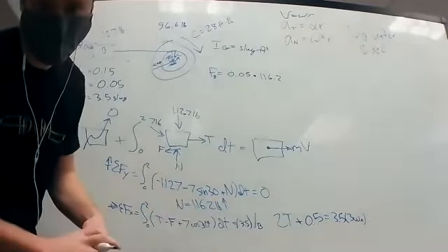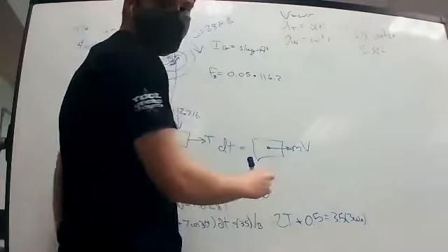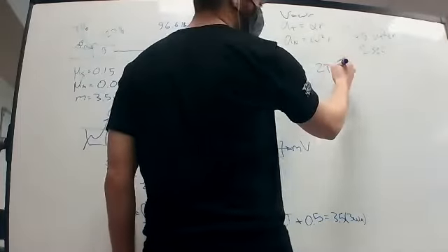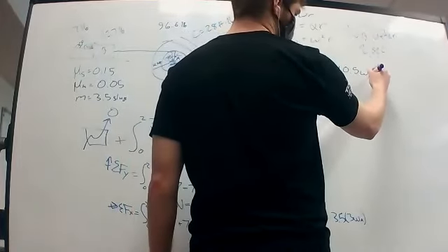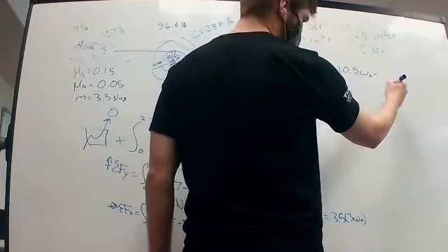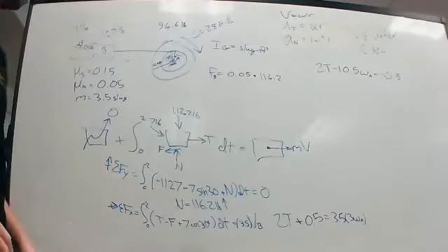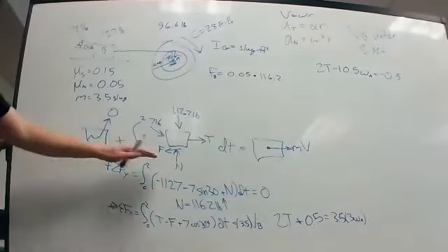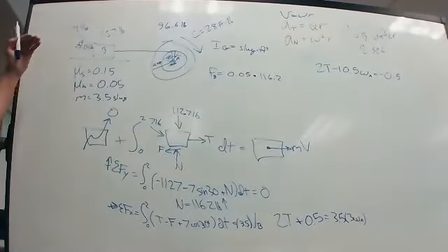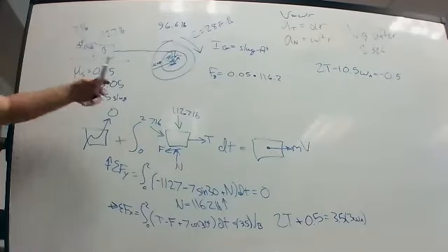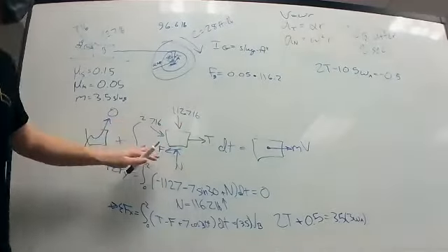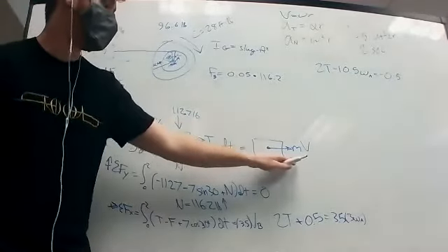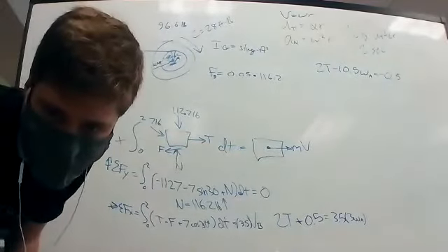So here we have our first equation, and they rewrite it to be 2T minus 10.5 omega A equal to minus 0.5. So that's our first equation there. The process so far has been setting up these diagrams when they say that we're looking for speed after a given amount of time. So we have starting at rest, integral from 0 seconds to 2 seconds, free body diagram, kinetic diagram, or kinematic diagram, or whichever one it is.